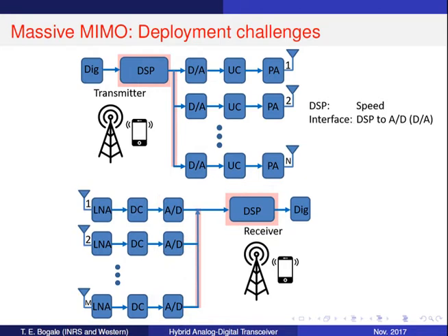In general, the power consumption and cost of the DSP units and digital interfacing cards are mainly related to the sampling rate and number of antennas. Therefore, for a fixed sampling rate, which is related to the transmission bandwidth, we expect a fairly linear increase in power consumption and cost in these two units, while still maintaining the desired optimal performance.